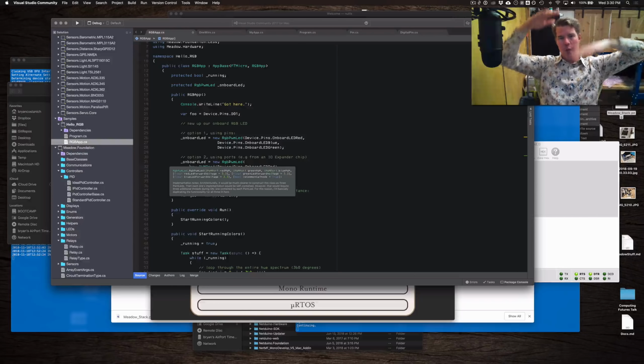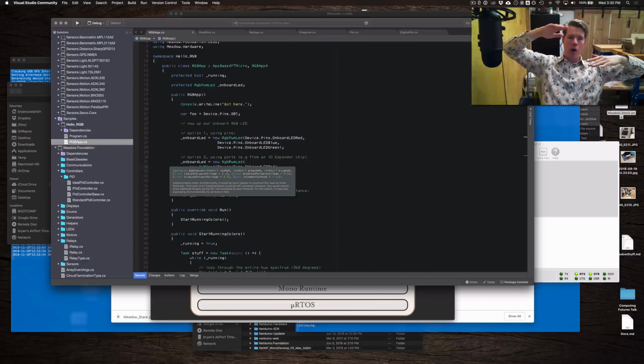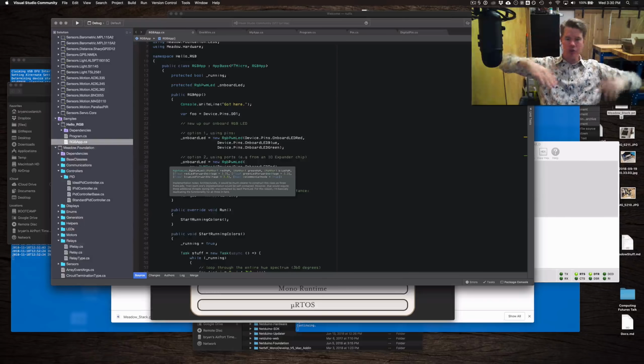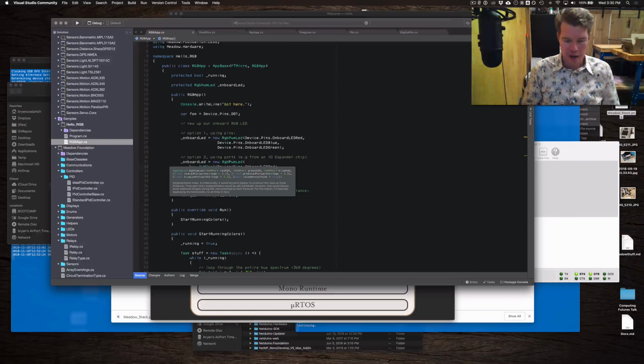It oscillates, and what that means is instead of having just on or off, 0 or 3.3 volts, you can actually get an average voltage, and so you can use a PWM signal to emulate an analog output. It's a good way to regulate the voltage for LEDs, and a lot of different motors require PWM signals for control, like servos and step motors, etc.